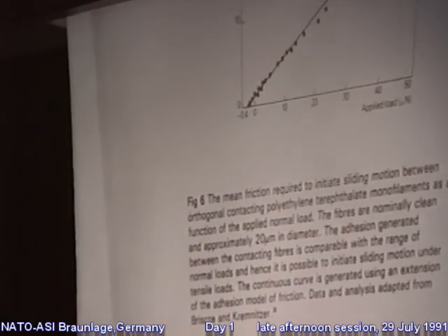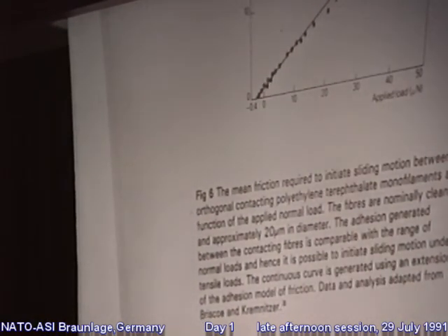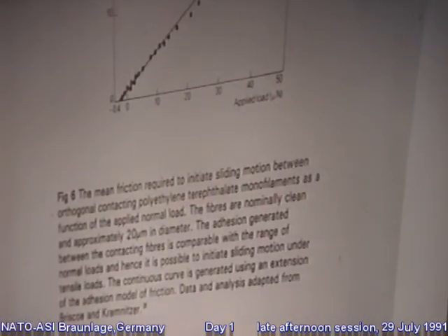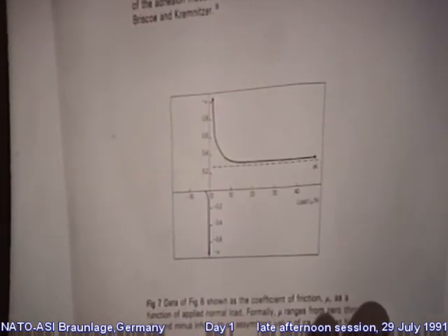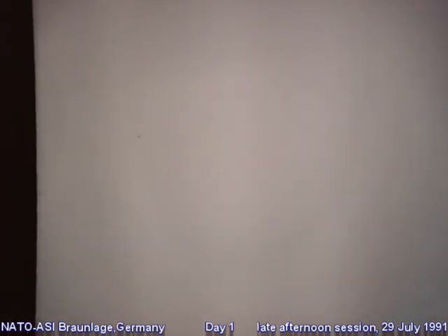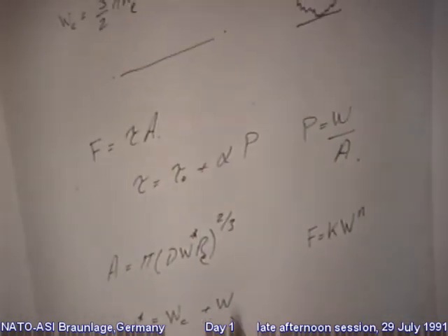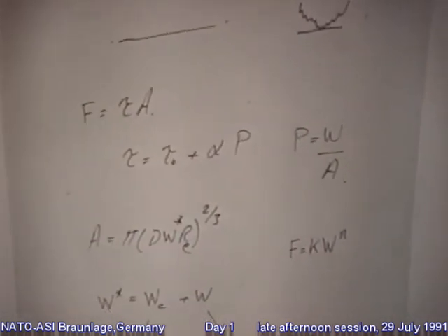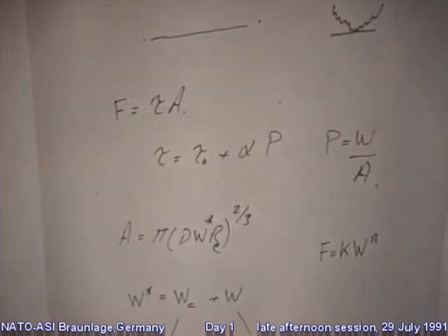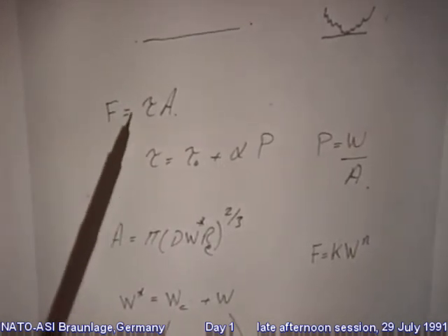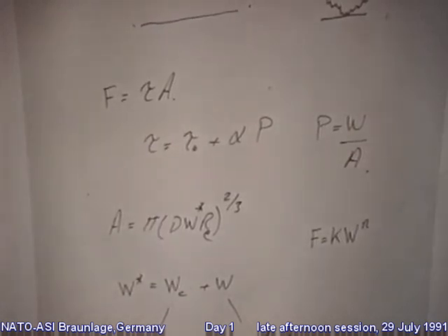That means that if you plot the coefficient of friction formally, then it follows this, goes to plus infinity, then comes back from minus infinity, and then to a point there. Now, this thing here, alpha, I'll come to that in a moment. Now, when I object to Kevin Kendall's analysis, which you mentioned, and here are the equations, what you would like to do is to use the adhesion model of friction, and there's this interface shear stress, which Singer will talk about a great deal later.